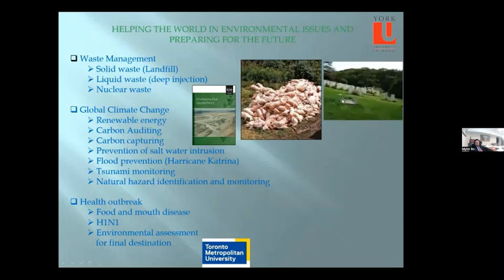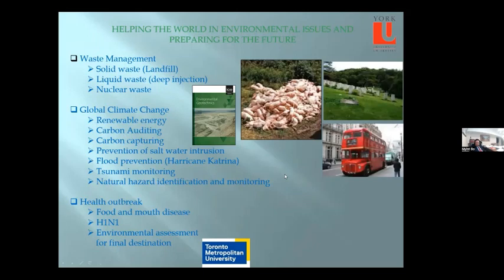In old days, most cemeteries were usually built on areas underlain by massive rock, with a slope to minimize infiltration. But in many countries and cities, they are on flat ground. They don't have such features to accelerate runoff and minimize infiltration. An example is Oklahoma City.